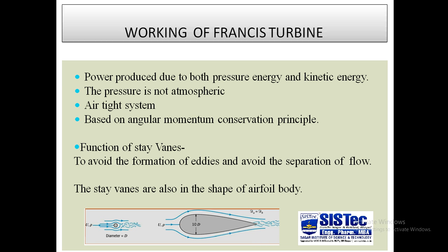The first point is that the power produced in the reaction turbine is due to the kinetic energy as well as the pressure energy, because here the pressure is not atmospheric. That means the pressure at the inlet is more and the pressure at the outlet is less. In the next slide I will show you how the pressure is changing.